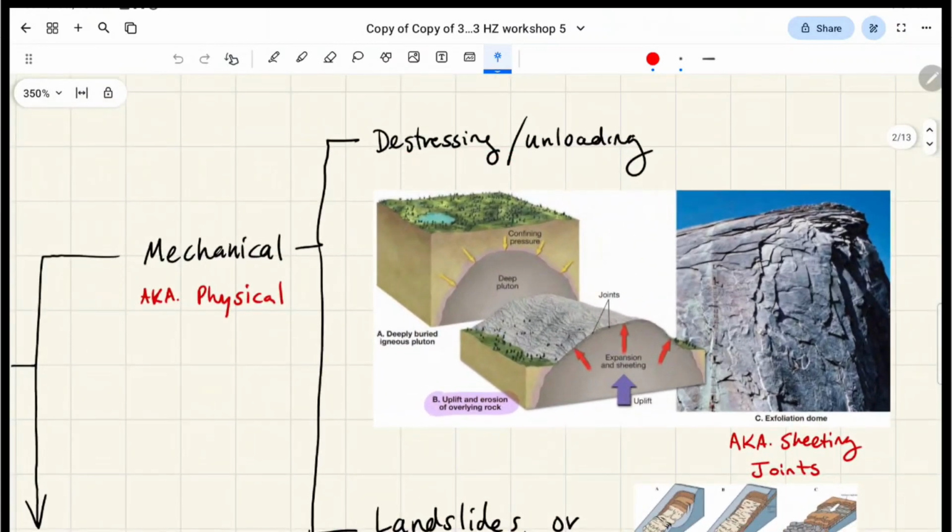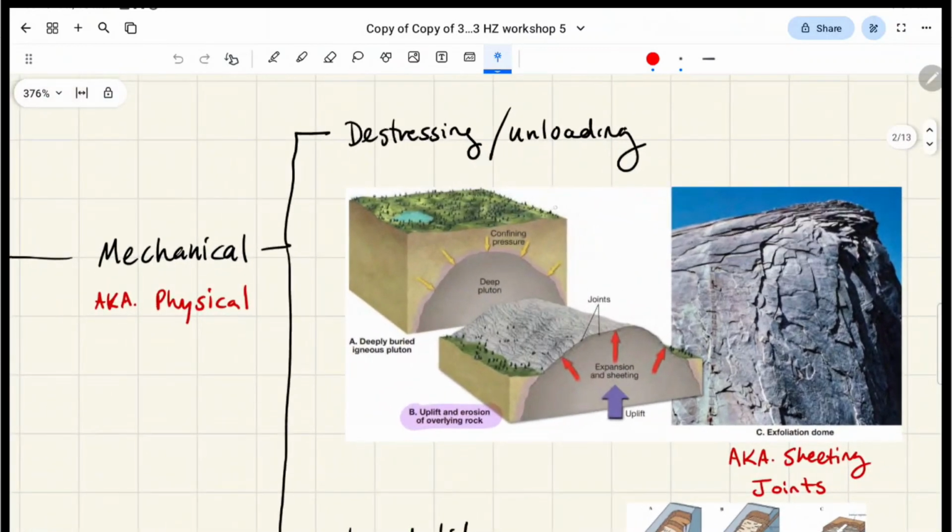So when you're talking about de-stressing or unloading, kind of two words for it, you can see there's this top layer of rock confining this bottom layer. And this term, confining pressure, is actually kind of exclusive to geotech, essentially. You're not going to see it in the structures or anything. Confining just means it's holding it in place, right? The soil's holding the other layer in place.